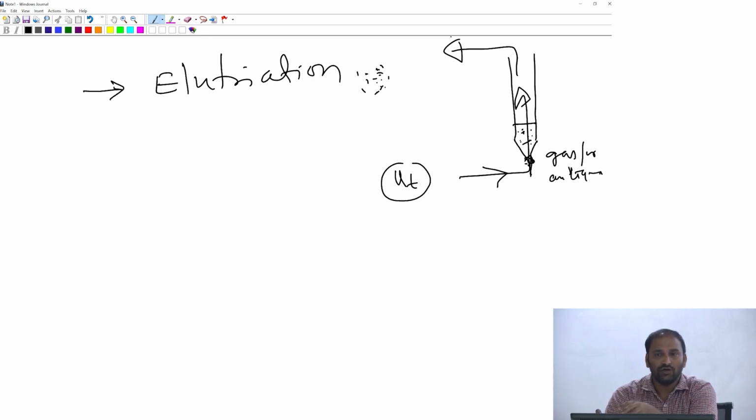So having an idea about the terminal velocity, also called the terminal settling velocity, is useful, because when you're talking about motion of a particle under the influence of gravity, it's basically settling, right? So depending upon whether the particles are smaller or larger, whether the Reynolds number is less than 1 or more than 1000, you should be able to come up with some estimate of the settling velocity of the particle.